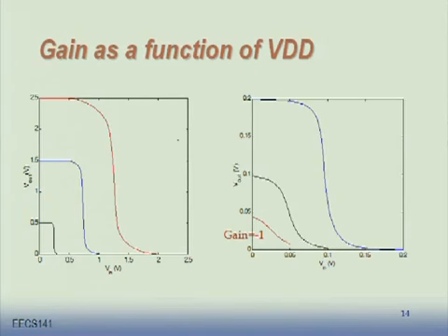There are applications that don't have to run very fast, and they can operate in subthreshold. I have not talked about subthreshold models, but it's just showing that this whole thing, just put it in SPICE, and it's going to run in subthreshold up to some point. What is that magic thing that happens around 50 millivolts where this thing stops working? Well, this is 2 VT. There is some significance of the 2 thermal voltages where things just don't work anymore. I won't talk about that much.